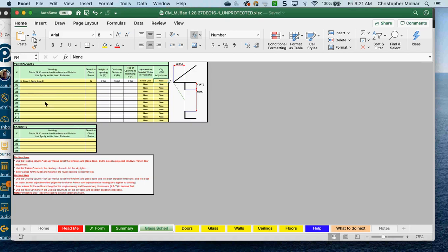And again, height makes a difference. If you have windows facing all 4 directions of your house, and they're the same windows, the same type of glass, you're going to have 4 lines for that window because direction makes a difference. Doesn't make much of a difference in heating load, but makes a big difference in cooling loads.